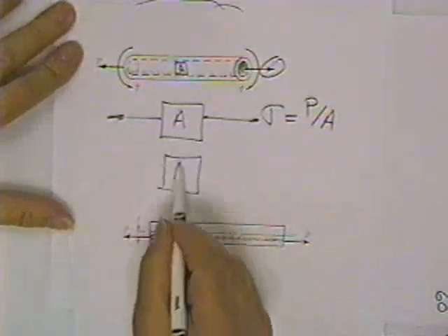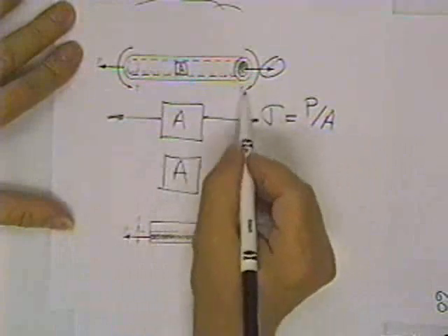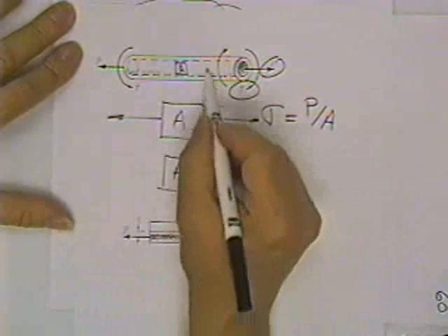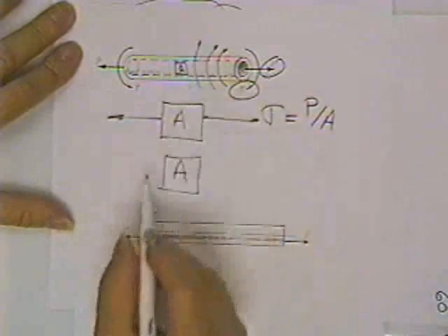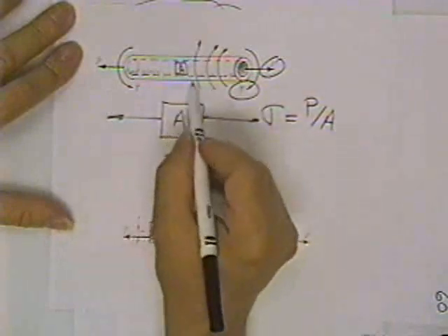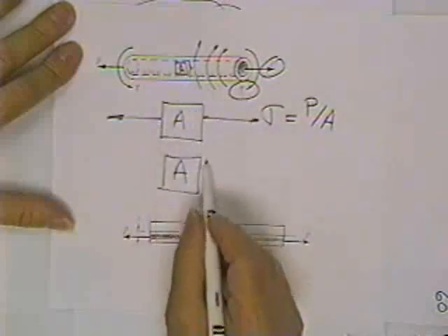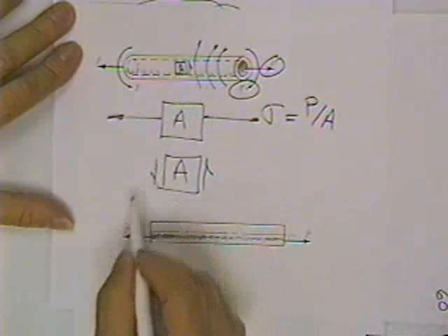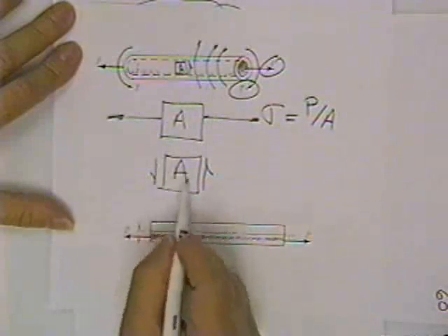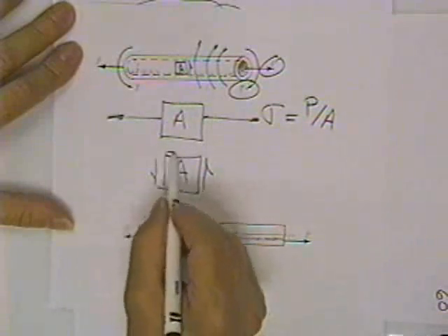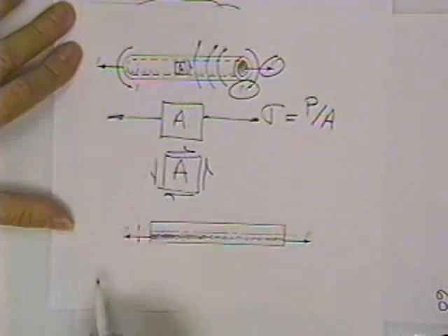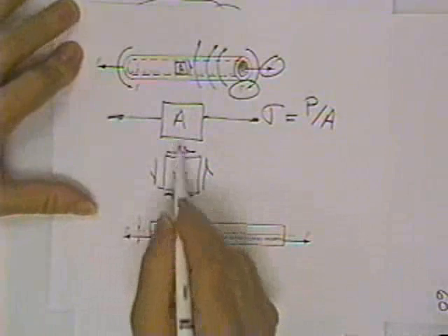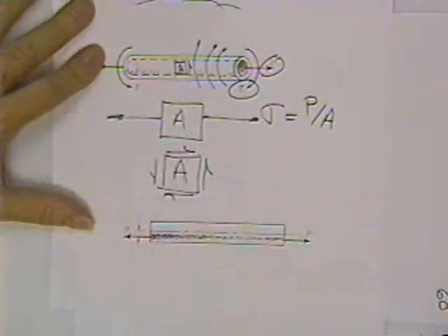Then you have to draw me the same postage stamp and put on there nothing but the twisting. Well, the twist comes around and he comes around and he comes around. You remember how torque causes shear? He causes a shearing stress like that. To put that in equilibrium, one on this side will appear. To keep these two from going counterclockwise, these two will appear. And the total sum of what's happening to block A will be the sum of these.